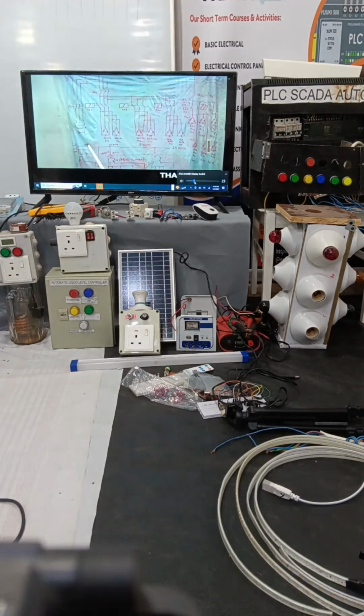Good morning, friends. In the last session, we have seen the overview of our 1500 kVA control panel power diagram and control diagram. So here, there is one main incomer which is feeding the copper bus bar system. Bus bars are copper flat bars. They are used instead of flexible wires due to some technical reasons. Then from the bus bar, there will be one branch breaker Q1.